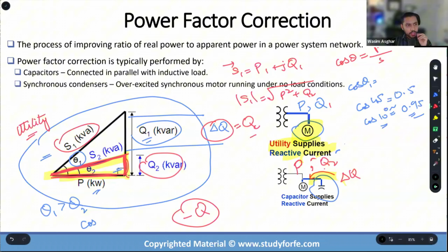So what we have, and this is where I find people just losing track of what power factor is. Because if you just focus on the equations, you feel like all you gotta do is just punch in the numbers, right? But having this understanding that when I inserted a capacitor in parallel, this capacitor was able to provide reactive power locally, right? And the utility now no longer has to provide this extra bit of reactive power.